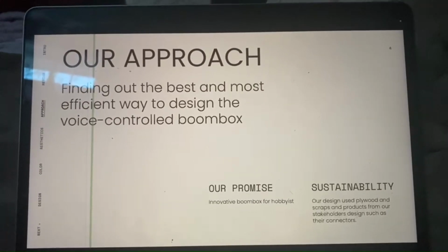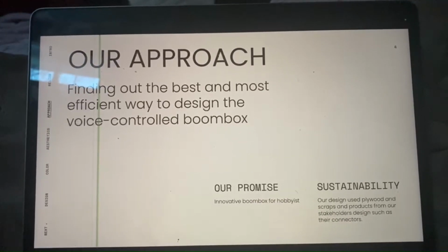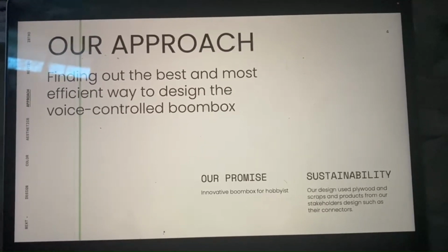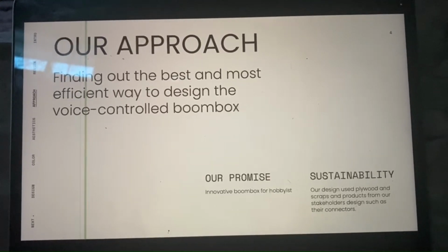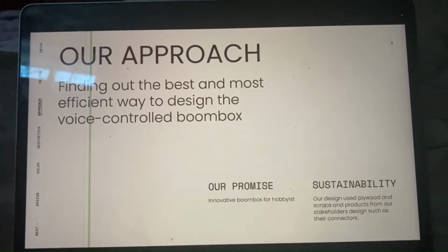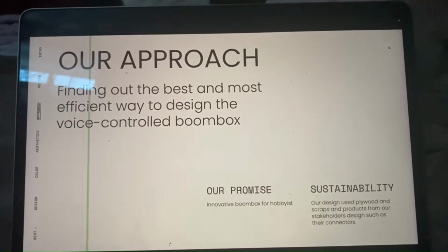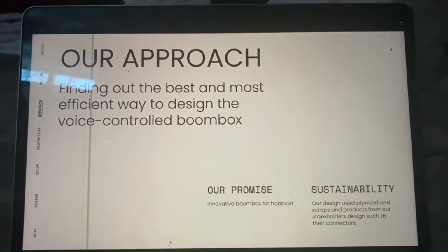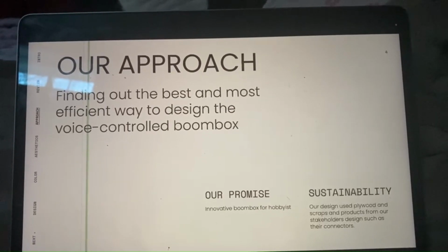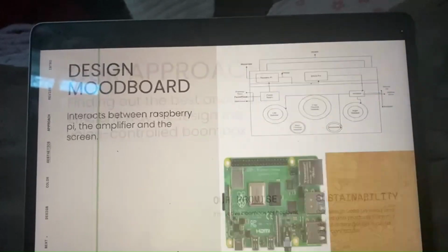Our approach is finding the best and most efficient way to design the voice control boombox. And by saying this, we really just want a boombox that works and works well. It goes from 200 hertz to about 20 kilohertz, which is proving a bit difficult because we're having some problems with the amplifier sometimes when it turns to a certain volume. But we've also somewhat fixed this because some of the connections were loose, and we've done this by getting better connections. And when our enclosure is done, we're going to heat wrap it and solder the remaining areas.